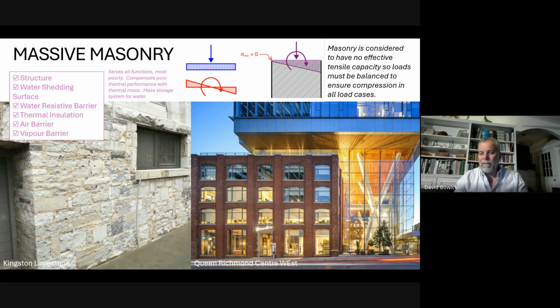So the rule of thumb is something I don't remember. I've seen this published somewhere, but the rule of thumb is something like 2 wythes of brick will carry 2 stories, after which you add a wythe for every 2 stories, I think, something like that. Anyway, so you start with 2 wythes of brick, which is about 190 millimeters as your basic unit, and you get thicker the taller you get. And then you might add pilasters for your concentrated loads. So that would be for a brick wall. The one on the left is a limestone wall from a heritage building in Kingston, I believe.